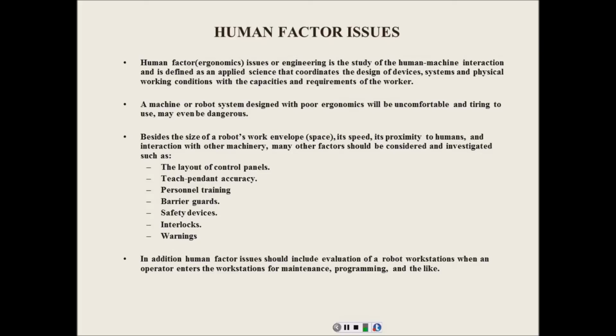A high-speed teach, what's the limiting speed for jogging a robot? The maximum speed. 250 millimeters per second, which is roughly 10 inches per second. Some of the robots, the KUKA and the Big Fanuc, have what they call a high-speed teach, which has nothing to do with jogging the robot. What it does, it allows you to run the program in manual mode at full speed.